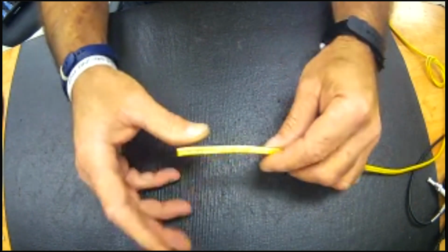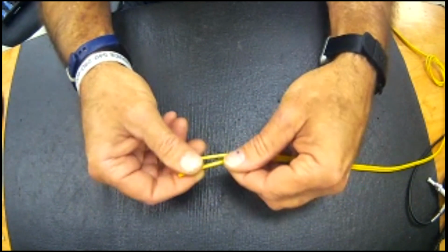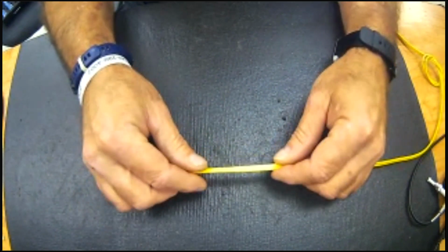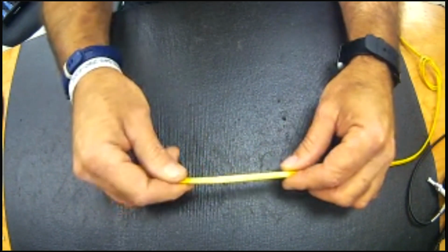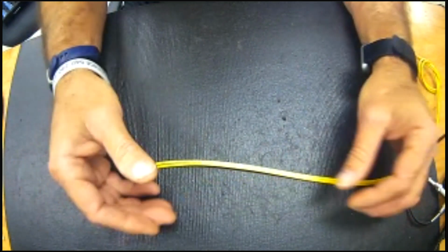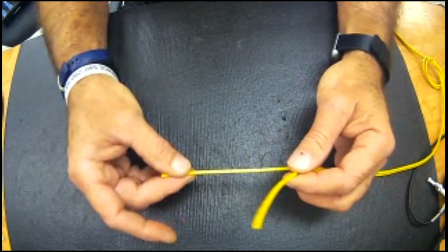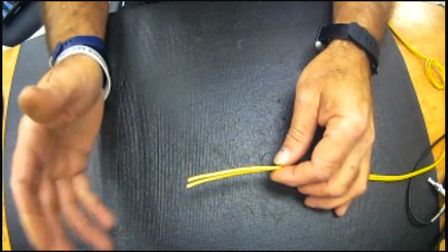And we have to explain to them that duplex is literally just two. Simplex is just one. Unfortunately, I don't expect purchasing people to know this, but you need to spell it out for them, either written or otherwise, that duplex and simplex don't actually tell us anything about multi-mode or single mode.